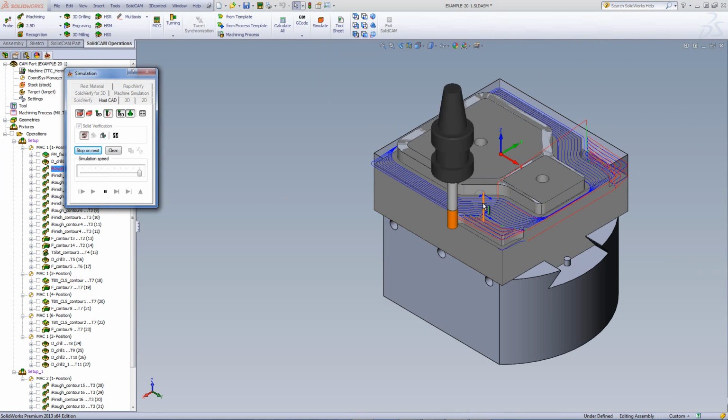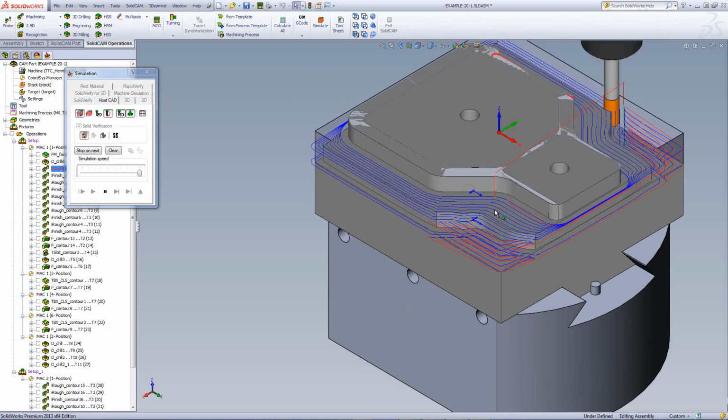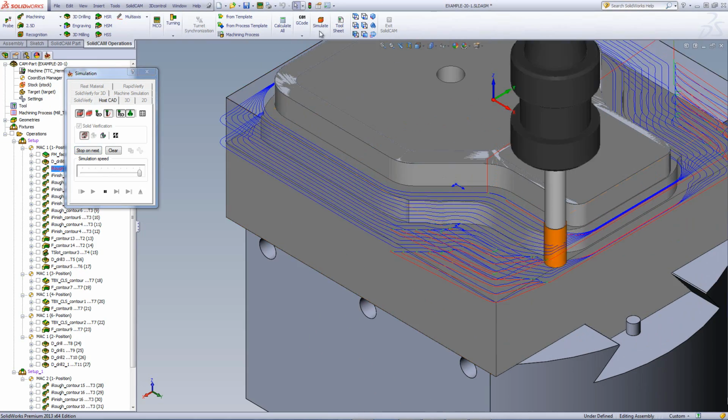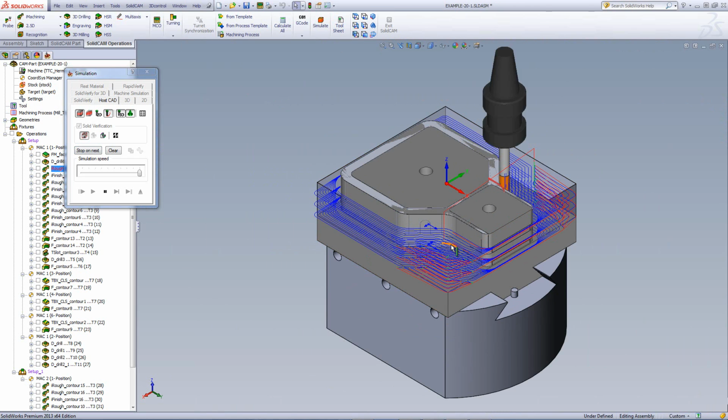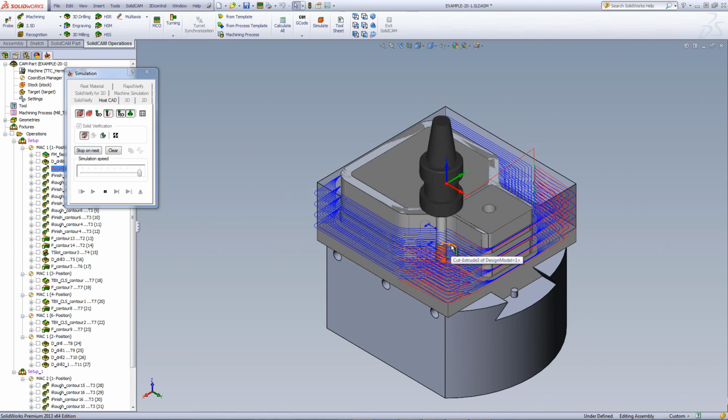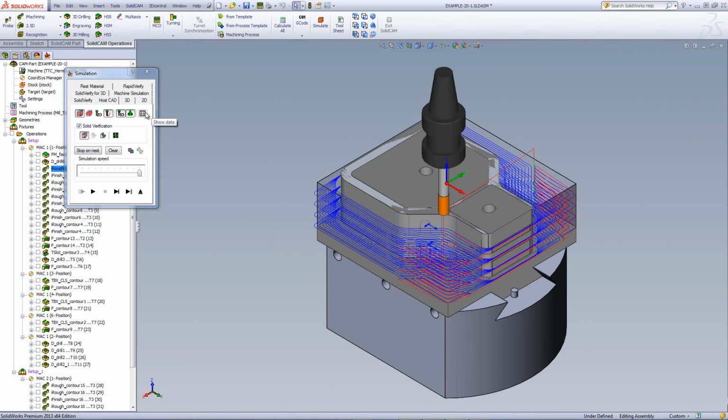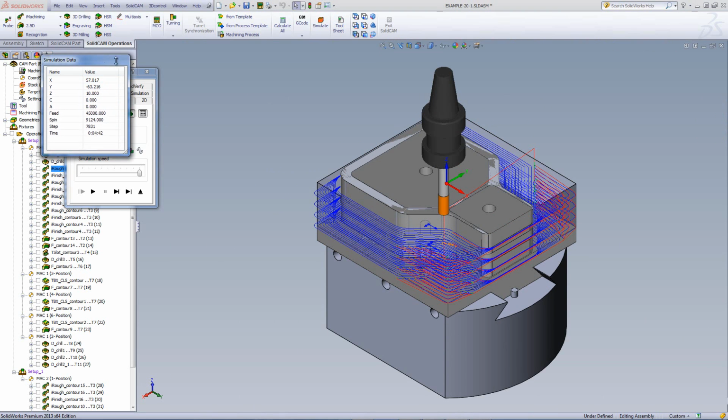You can actually see the tool path itself over here as well, how it's actually doing a morph spiral on the outside and then trochoidal on the corners itself at the very, very end. And it goes down the amount of step that it needs to go down in this particular part.